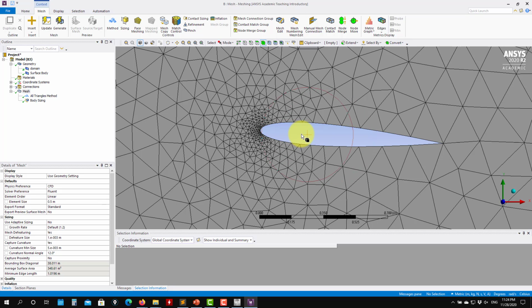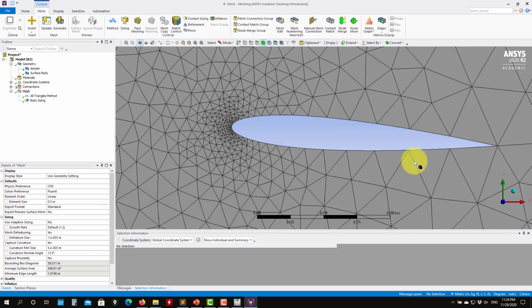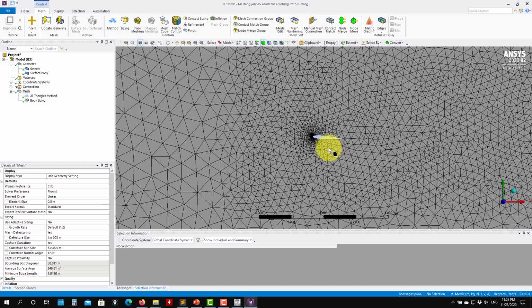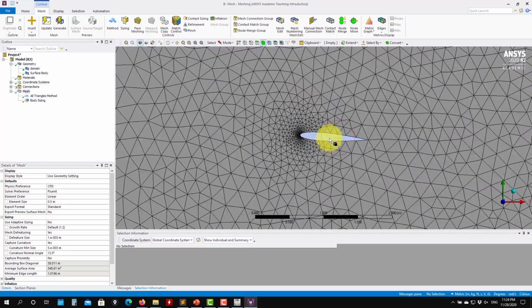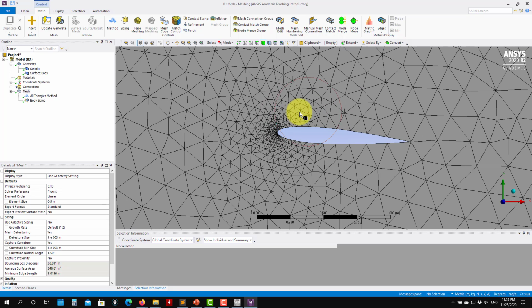You need to resolve the boundary layer, and the boundary layer is a very thin region. So with this element size, we are not resolving the boundary layer, but also if you have vortex shedding or some structures detached and separating, you are not resolving those structures with these elements. A lot of these length metrics are related to turbulence modeling, so there is a course related to that, and you are going to understand better all those structures. But your mesh is strongly related to turbulence, and turbulence in CFD is the most important thing. So far in the potential methods, turbulence doesn't enter. Here in CFD you need to define it, and there are many models.